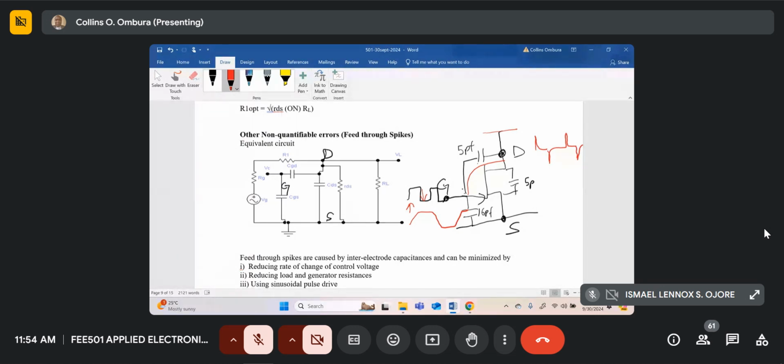So if you look at this circuit over here, when the signal is going positive, the pulse, let's assume you use one frequency of this square wave, the most dominant. Remember, a square wave has a fundamental which will contain the most energy. So you can use linear analysis.